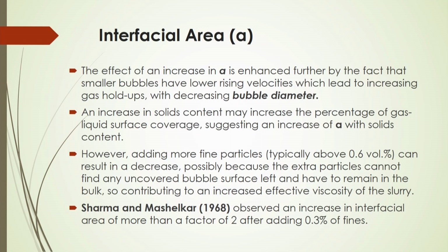So that it contributes to the increase in effective viscosity of the slurry. In that case there may be a change of specific interfacial area, and the increase in interfacial area will be more than a factor of 2 after adding 0.3% of fines, as stated by Sharma and Mashelkar, 1968.